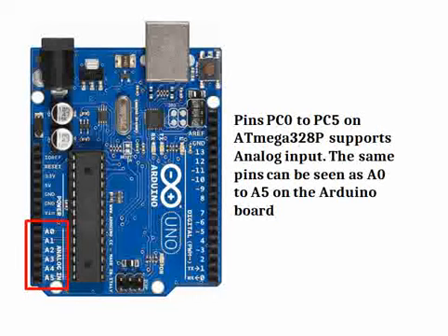And apart from the interrupts, one of the important features supported on Arduino Uno is analog. We have talked about that in our initial videos. We said Arduino Uno supports analog inputs. If you see the ATmega328P microcontroller, the pins PC0 to PC5, that means a total of 6 pins, support the analog functionality. The same pins, PC0 to PC5, are pulled to the specific connector and are named A0 to A5. So any of these pins can be used for analog functionalities.